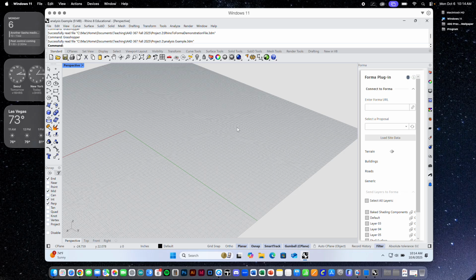And in fact, it's not lost on me that sometimes when you generate these values, like let's say energy values, more solar energy, less solar energy, you can actually use those numbers, that data, back into the recipe for your shading component. So you say, well, my shading component can either be really tall and spiky and closed up and provide a lot of shade, or it can be shallow and open and allow a lot more light in. And if you think about then how you can use those solar values to what gets more light or less light, where you need to sort of shade, where you don't necessarily need to shade, then you can actually use those numbers to inform the geometry for each cell.